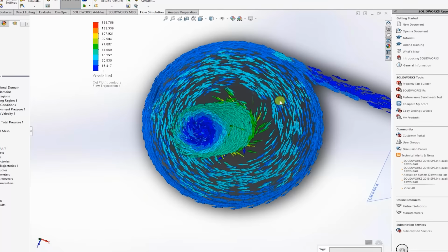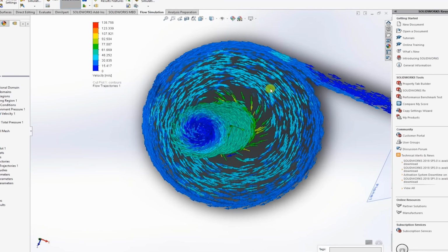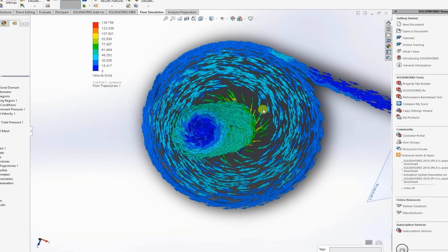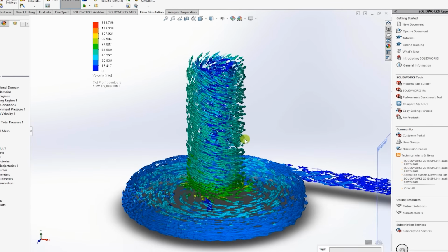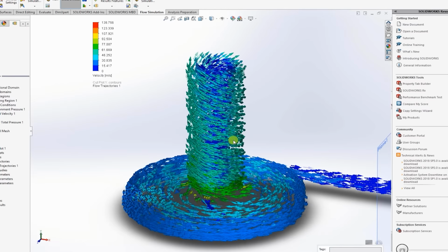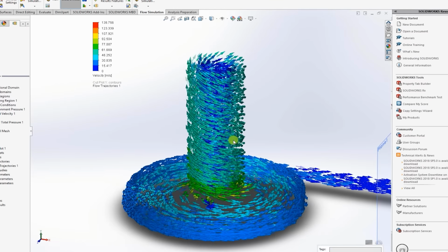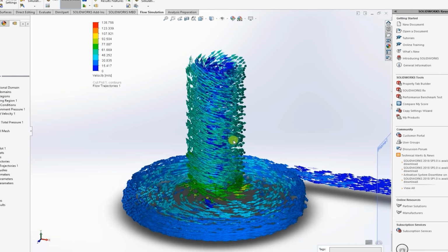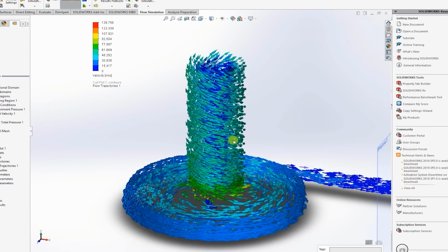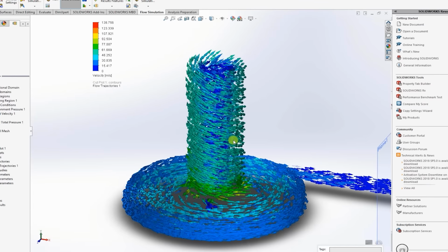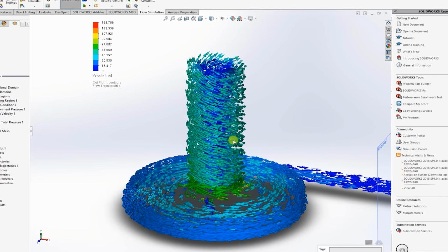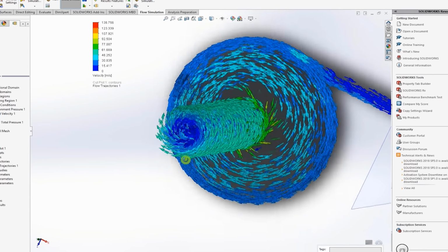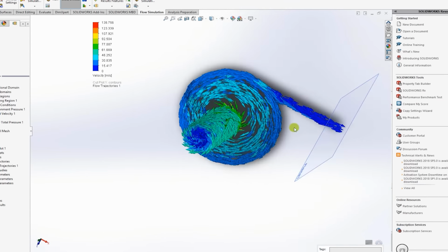This typically means that the pump has been designed badly, which in this case is true, because we are using a made up geometry. Because clearances are really important. You need to have the right amount of clearance between the impeller and the casing, because that determines how much vacuum the pump can generate so that it can suck in the inlet fluid. But qualitatively this result is not bad.